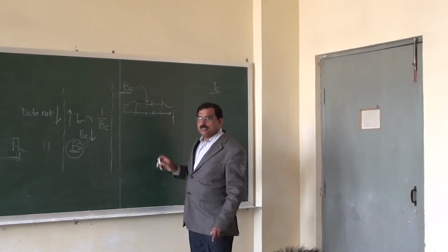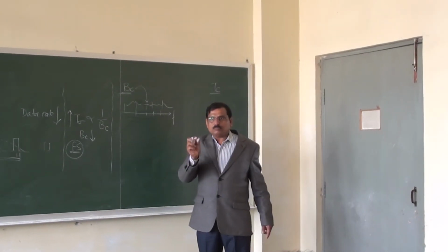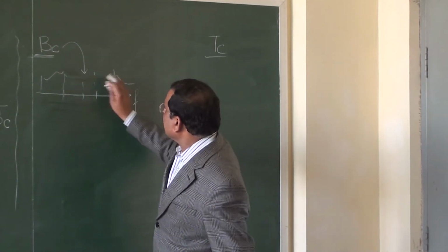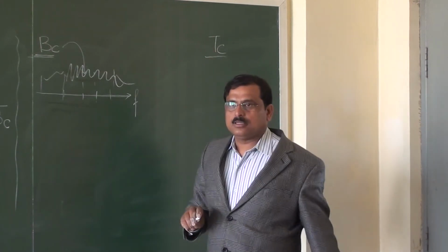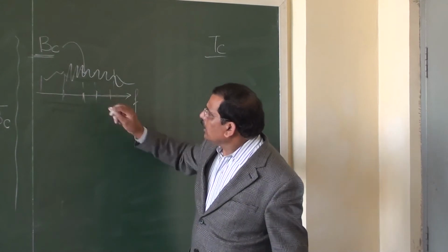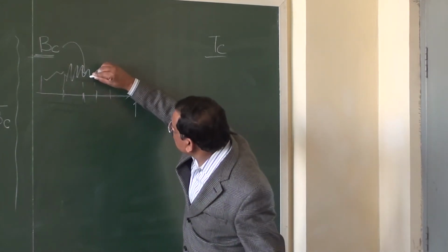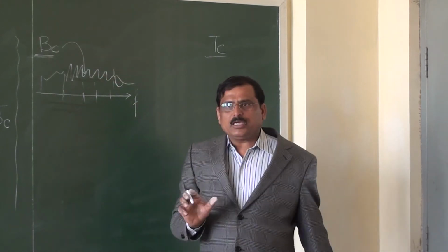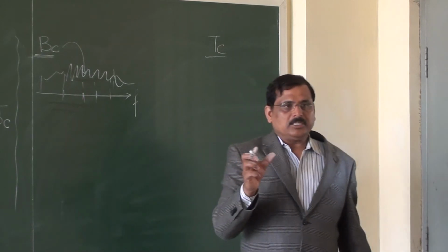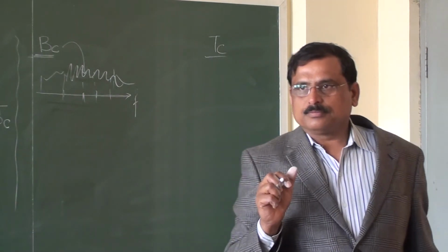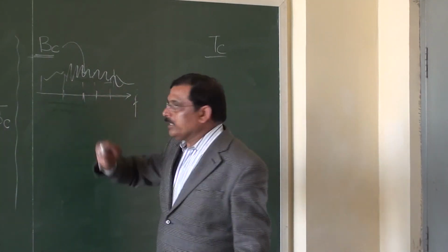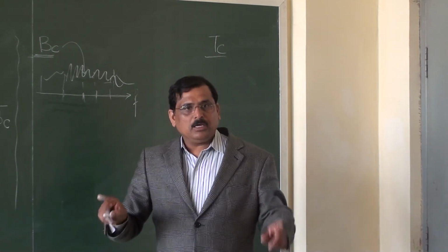And some channels are going to be such that even over a small frequency interval, they are going to show you much variation. It will be something like this. Something like this. So it simply means that you take any domain of the frequency, you will find only a very small span where, see, only during this interval we can consider, or maybe somewhere during this interval we can consider, the channel is going to exhibit the same thing. So you understand, this is one example of a small coherence bandwidth, and the previous one was an example of a wide coherence bandwidth.